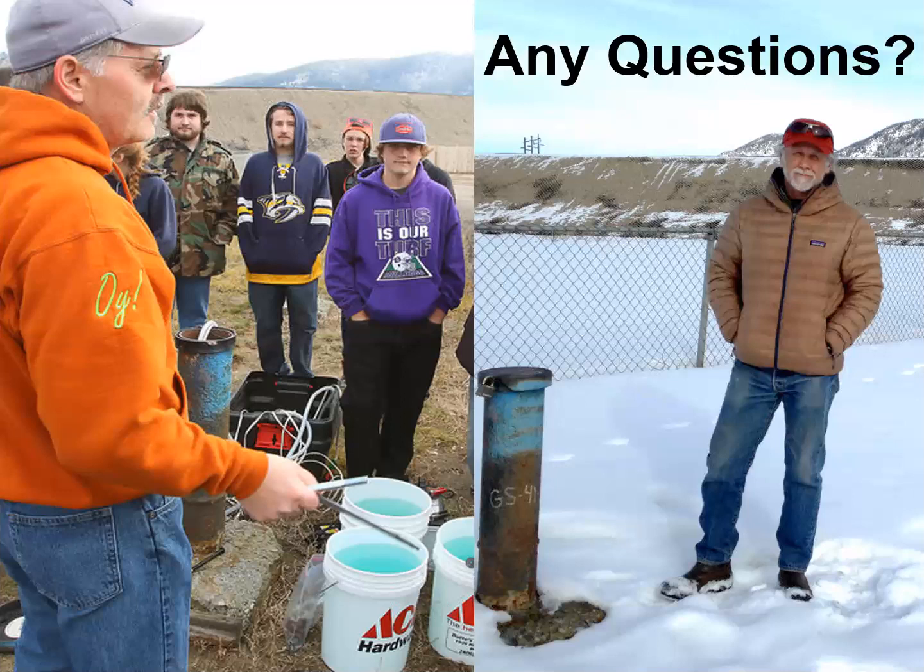Atlantic Richfield's consultants did aquifer analysis. The Bureau did their own aquifer analysis. We all agree, you measure a transmissivity, but we all came up with then converting that into a hydraulic conductivity of somewhere between 300 and 1,000 feet per day. So EPA's initial characterization of